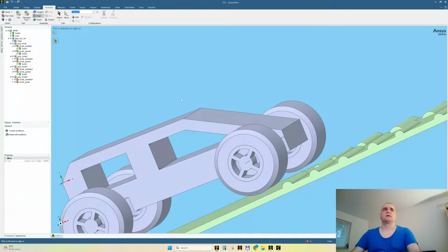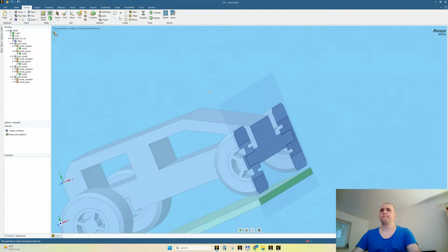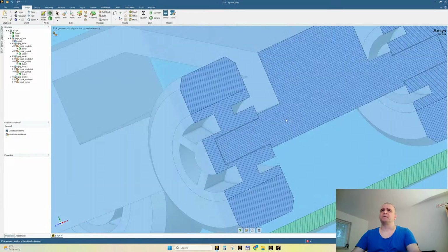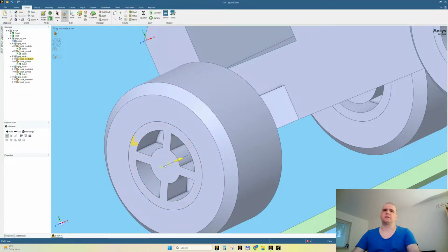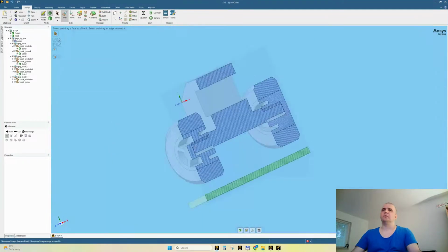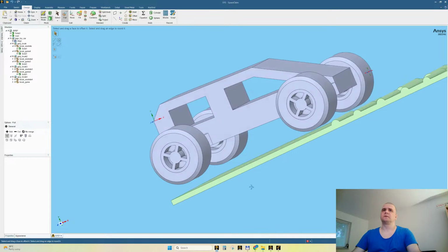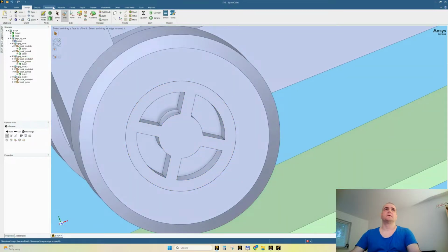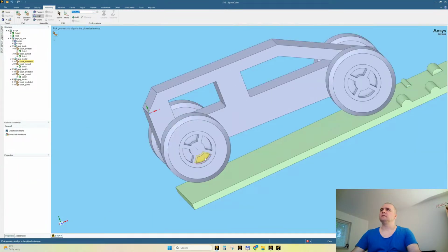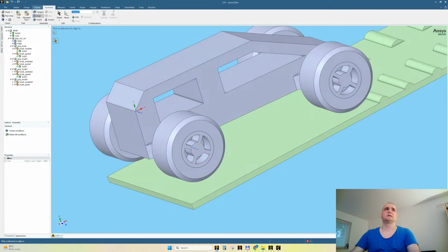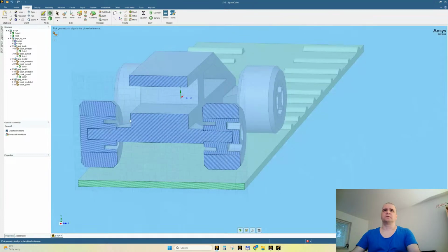I think we're in luck. Perfect. And I think it is the same also in the back here. No, we need to align here. Assembly, align. Let's see if I have the proper alignment here. I will hover, select the axis, design, section mode. Perfect.